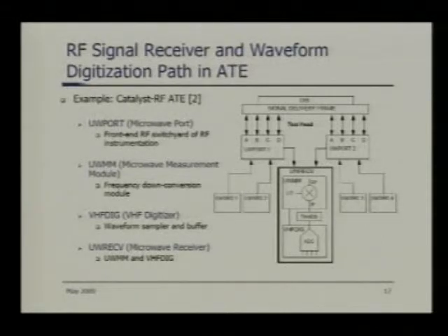I'm going to discuss what is there in the automated test equipment. Like I mentioned, in the case of an amplifier, you have to apply an RF test signal and capture the RF test response waveform. So you have to have an RF signal generator within the ATE.